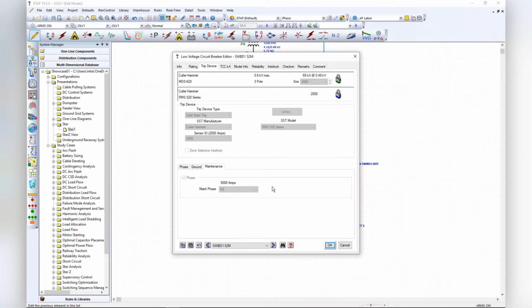So your typical instantaneous might have a band of about, I don't know, 5 cycles. These things, they make it like 2-3 cycles. I may be wrong on those numbers, but we're gonna see it now on the TCC. But that's what it's doing. It's just engaging that instantaneous override.